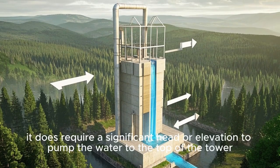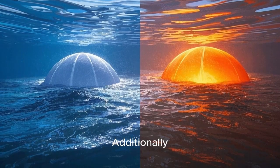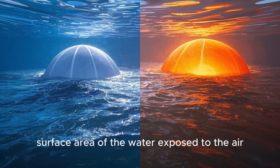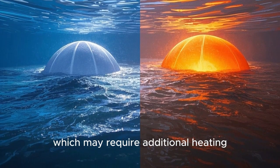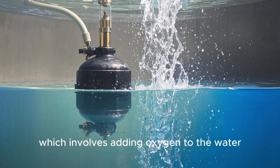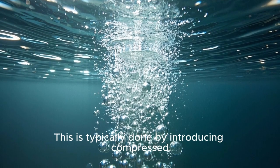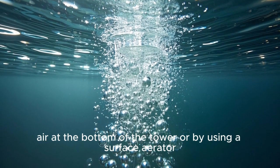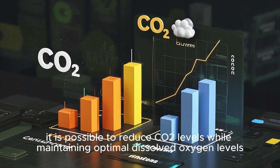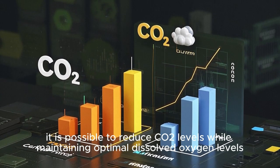However, it does require a significant head or elevation to pump the water to the top of the tower. Additionally, the system can lead to heat loss due to the increased surface area of the water exposed to the air, which may require additional heating. Nonetheless, splash aeration is often combined with aeration, which involves adding oxygen to the water. This is typically done by introducing compressed air at the bottom of the tower or by using a surface aerator. By combining degassing and aeration, it is possible to reduce CO2 levels while maintaining optimal dissolved oxygen levels.